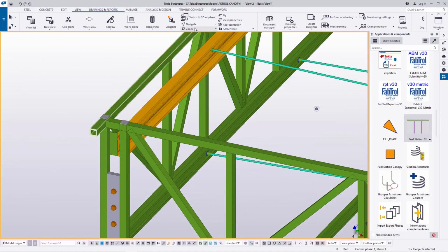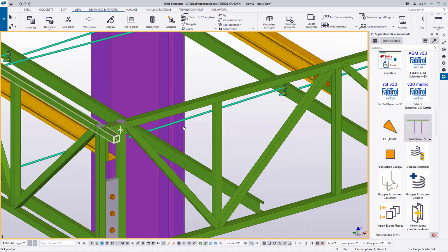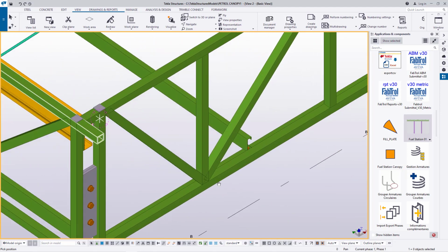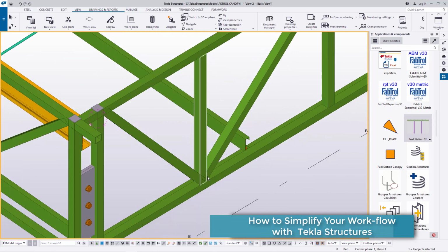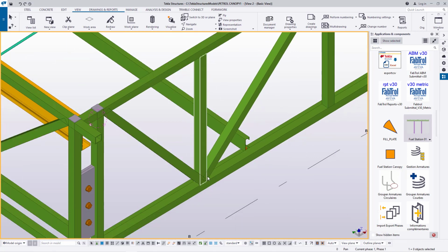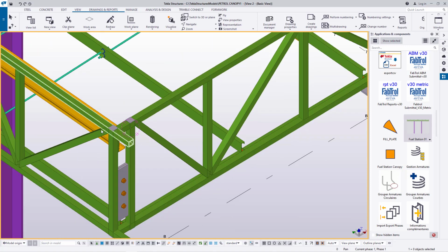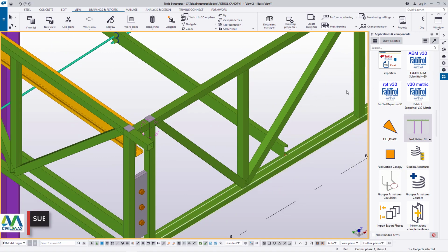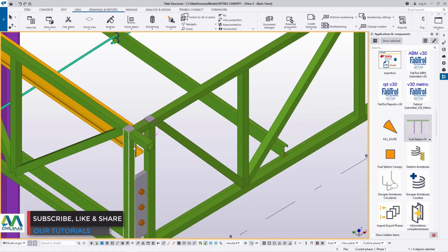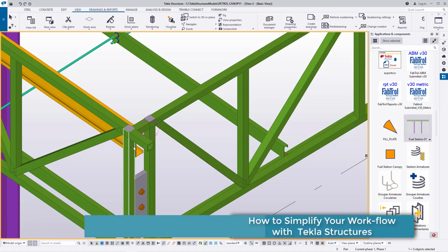Most of the time, what you'll face here is that any part where you used a macro to create a weld, such things will appear. That's what I was trying to share with you, that you always start ahead of time. If you find yourself in a situation like this, where the weld you created has been slightly messed up, you just come here and modify it as you modify this particular structure to match whatever you want. In any case, this structure matches whatever was needed. We just modify this and generate your drawing.